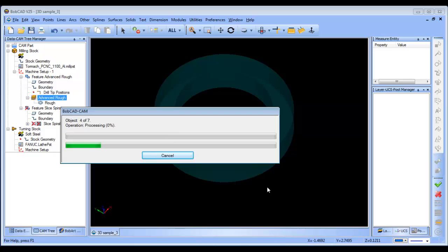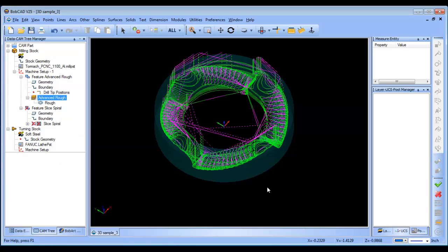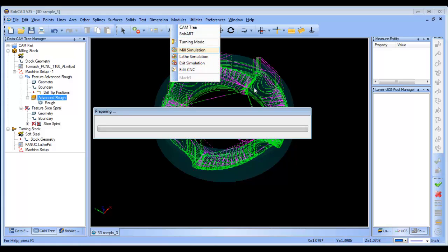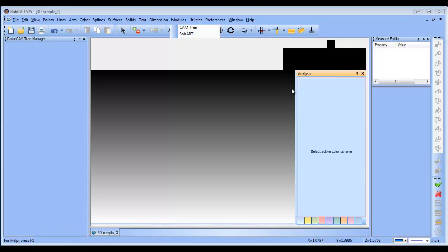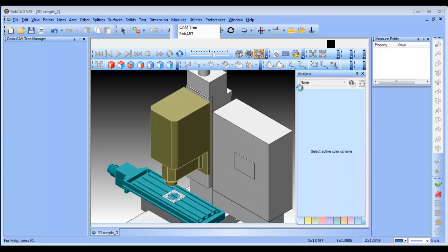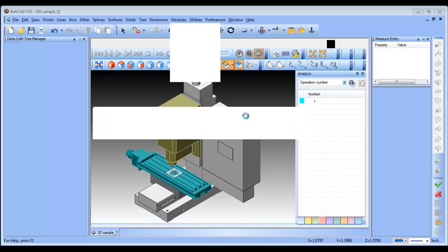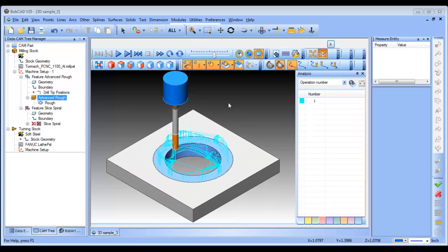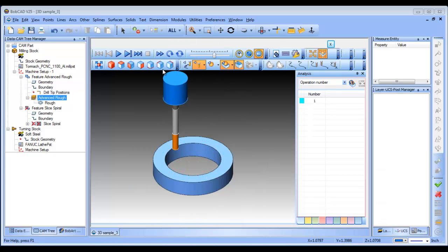And then now, the other thing is, because you're cutting deeper and you're cutting basically side milling here, you can increase your speeds and feeds, maybe 3 times, 4 times, 5 times. It depends on your spindle range and how many flutes you're working with. And there are some pretty neat calculators that are out there that you can use to help you deal with chip thinning and all kinds of other concepts that have to go along with high-speed machining.